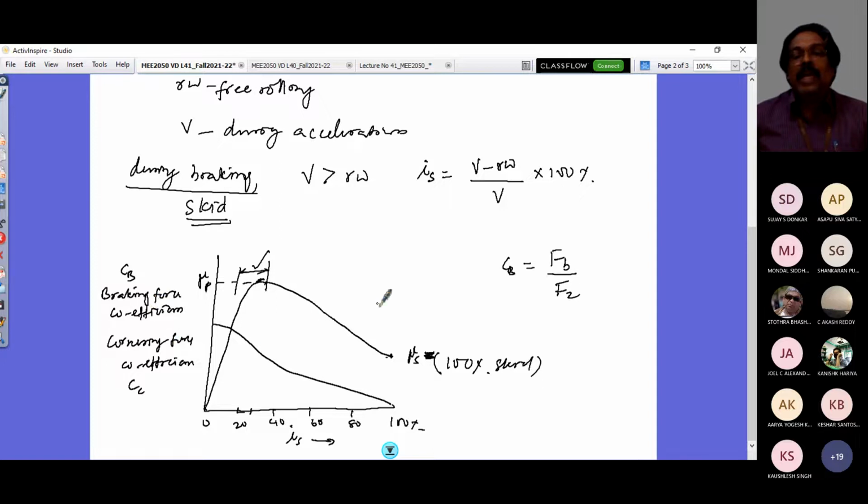And this diagram is drawn for a particular slip angle. That's very important. So you are going to see something called a friction ellipse. All in tire dynamics we'll discuss. The slip angle requirement increases whenever the side force increases. So I take one particular slip angle and then I look at the variation of my braking force coefficient and cornering force coefficient like this.